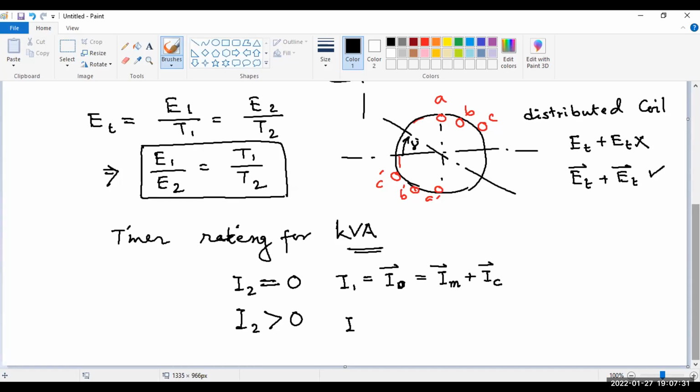Sir, when any load is connected across the secondary, current flows, which opposes the primary flux and tries to reduce the overall flux. But from the EMF equation, we know that the flux is constant as long as V by f is constant. So flux should not depend on the load. Hence the core flux should be the same at load as well as at no load. Therefore, there should be a compensating current to compensate the lowering of the flux.